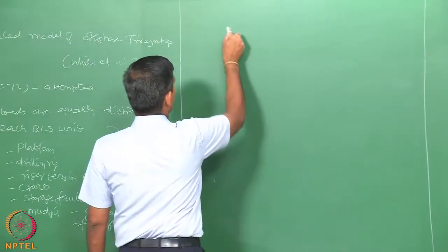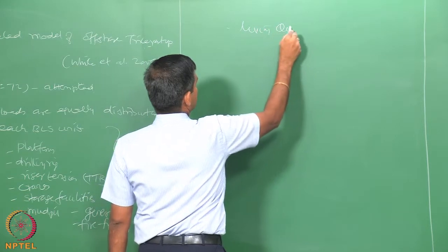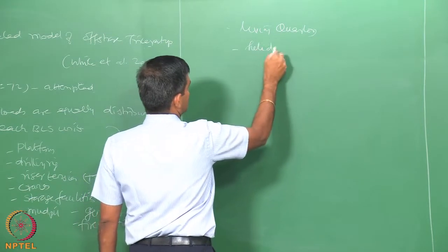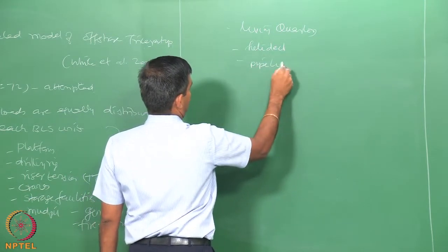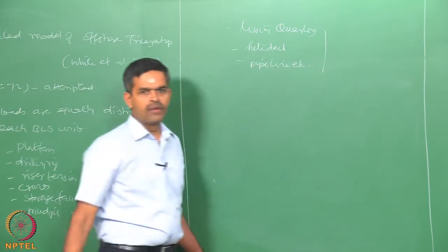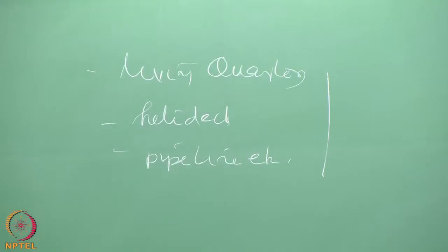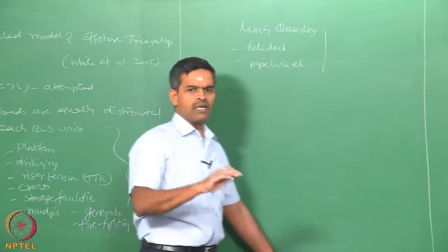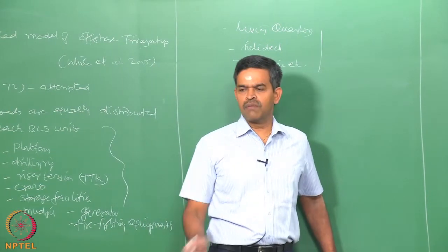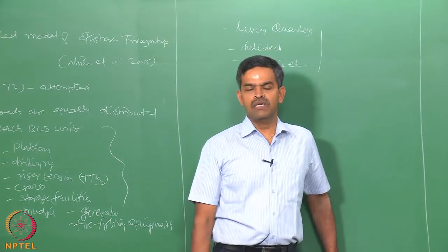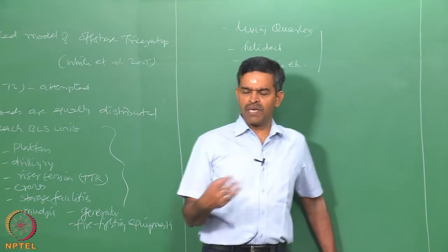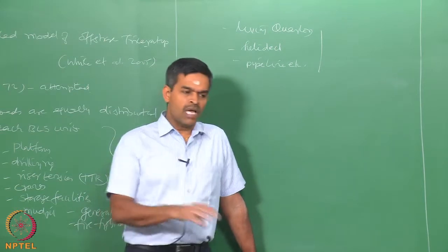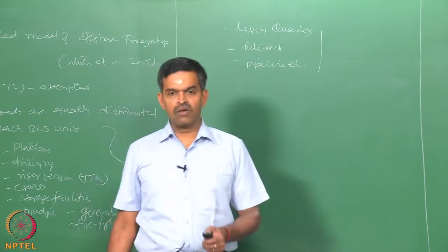Of course, the models include the weight from the living quarters, the heli deck, and pipeline systems, etc. Mass of each of the above is calculated and used in the present study. Generally, the drilling rig will be placed at the center of the deck to have a similar mass distribution, but in this specific configuration the drilling rig was placed on top of one of the BLS, so that the risers are planned to connect to the moon pool very easily on the BLS unit. So, this will help effective use of the deck space on top of the triceratops.